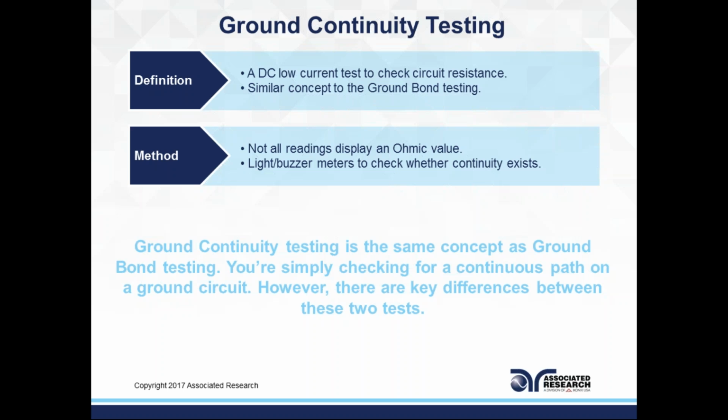So if the standard requires you to just check for continuity, but I'm a medical equipment manufacturer and I want to make sure that everything that leaves my facility is not just tested to the minimum value but to more than the minimum value, in this case I'm going to do a ground bond test, because I'm selling somebody $25,000 equipment. I'm selling somebody $100,000 equipment. I want to make sure the ground circuit is there, and is working properly after the production is done.